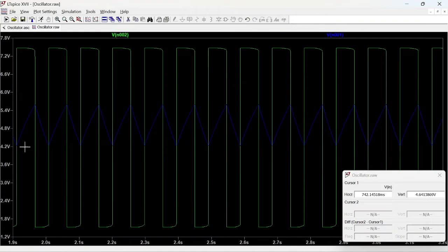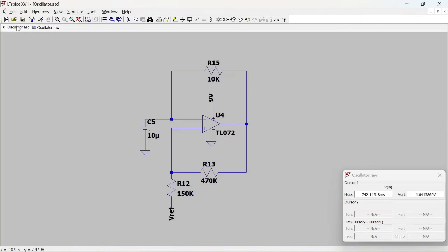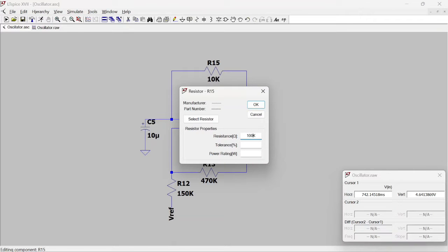And if you remember, this is very indicative of where it goes. You remember that threshold part where I said the Schmitt trigger is triggered. It's around here and there. So in between that part, we have this charging and discharging of the capacitor, and that's what powers that Schmitt trigger to change the state, etc. So this is our oscillator, and if we increase this, say 100K,